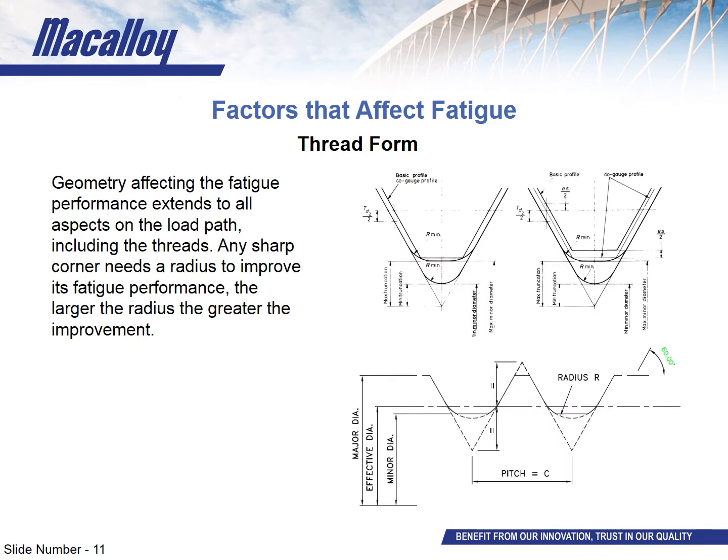Just as geometry affects the fatigue performance of the anchorages, the geometry at any point in the load path can affect the rod's performance in fatigue. Any corner or change in thickness can result in the stress concentrating at one point, with the sharper the corner is, the greater the concentration. Now, while the stress evens out in areas away from the transition, the stress is compounded at that corner, forming a stress raiser, otherwise known as a stress concentration area. Just as with bending moments, a concentration of stress at one point correlates to a larger stress range as that load fluctuates. Now this in turn reduces the fatigue life as stress raisers are hotspots for crack initiation.